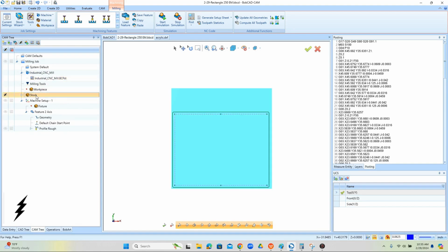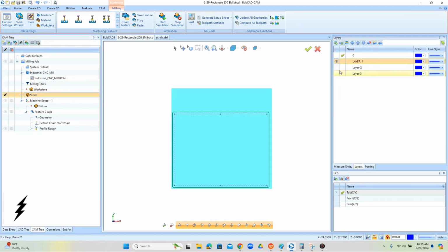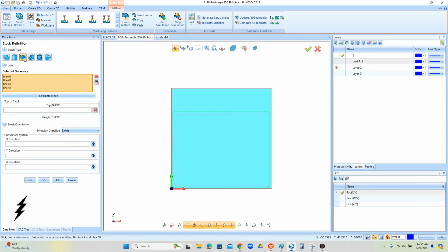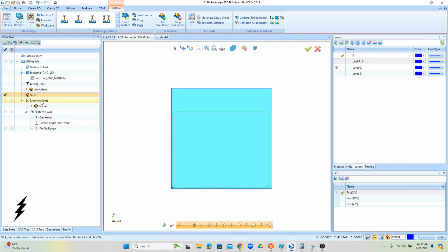This is our stock geometry. So the way that I set it up is I always draw the stock as a shape, and then you can just select it. So this is a wireframe, so I can clear my selection. So it's looking for a chain for me to select. So I'll just shift left click on that, hit calculate, and now I have my stock defined. We're always zeroing at the top corner on this setup on this table, and then on the top of the material.